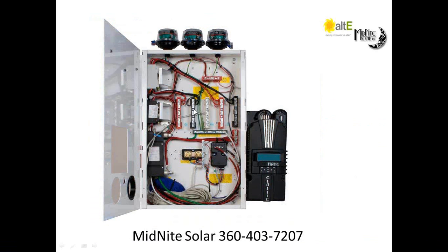You'll notice there's literally set screws. So you strip the wire, put it on the screw, tighten it down. Battery cables bolt onto the big lugs. Charge controllers are all pre-wired in off the breakers. It just makes a really nice, clean, easy to install scenario. And like I say, I'll talk a lot about specifics on inverters and different situations in a little bit.